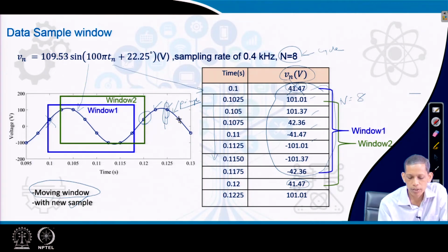When the new fresh samples come again, the relay has by that time already decided, and for the fresh samples it again computes the phasor and goes for the processing of its algorithm. That is why in this interval of time the relay has to accomplish data acquisition, compute the phasors, and then make the corresponding decisions. That is the typical relay performance that you achieve.